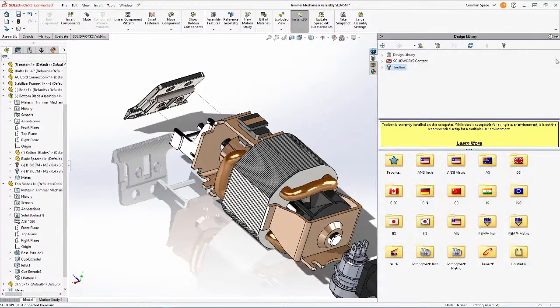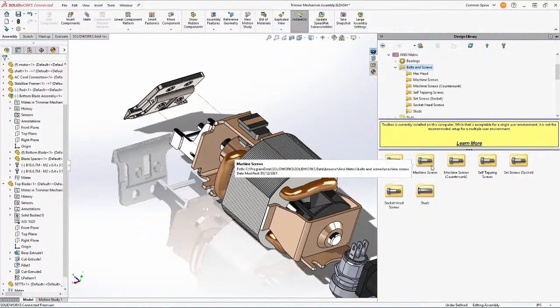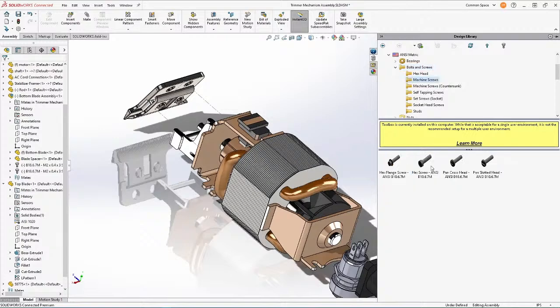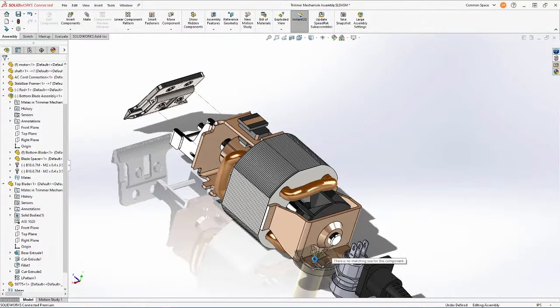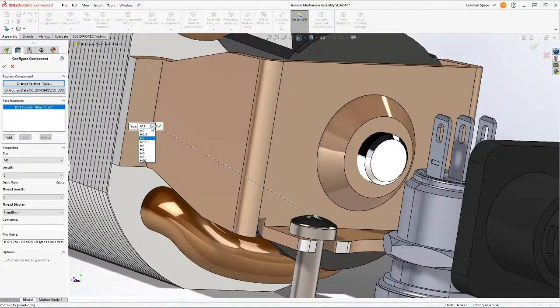All right, so we're going to need to constrain this motor enclosure with some screws. For all of you SolidWorks users, you're very familiar with Toolbox, but it's now in 3D Experience SolidWorks. For those of you who don't know, it's basically like having an entire machinist library right at the palm of your fingertips. You can see as I drag and drop a screw in there, it's automatically going to resize to fit the hole that I need, which saves time for modeling and mating standard components. And as I said before, it is the latest functionality as of this latest release.